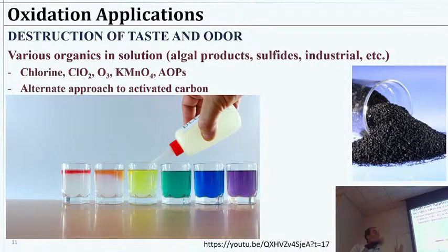Okay, some other applications, and those were iron and manganese removal, would include arsenic applications. Some other applications of using oxidants might just simply be changing the color of our water. Also taste and odor. So we can have various chemicals. Sometimes it could be hydrogen sulfide. Already talked about that a little bit from groundwater. But it could be other stuff.